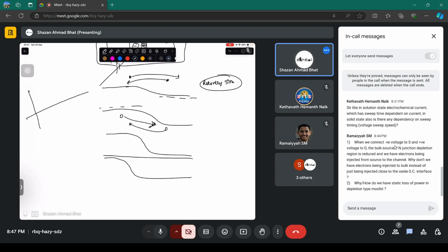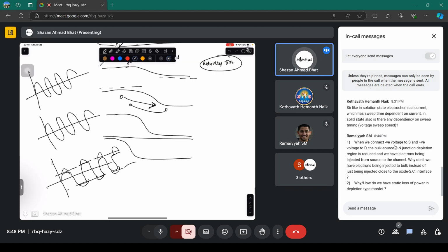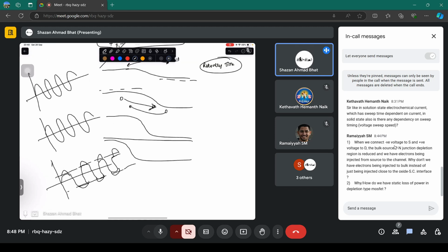Let's say if you give a sinusoidal voltage at the input and you expect a sinusoidal voltage at the output, but maybe due to some reason you get a voltage output like this. It clips off these particular ends, and that may happen because the diode is not able to follow the voltage change you have applied. That is what I guess you mean by sweeping. So yes, it is necessary that you sweep at the particular rate. You got the concept?